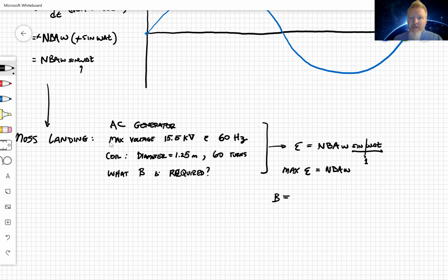That means I'm going to take the max EMF and divide by NA and omega. Remember that omega is 2 pi times the frequency.